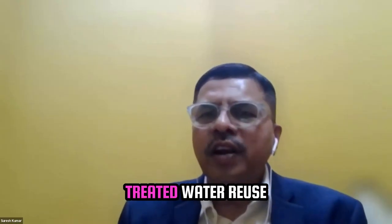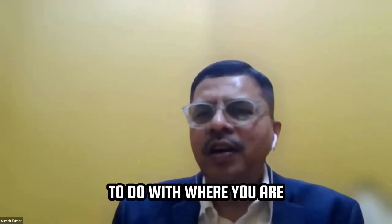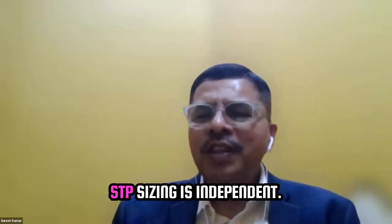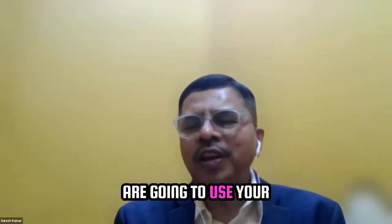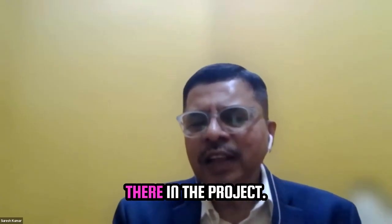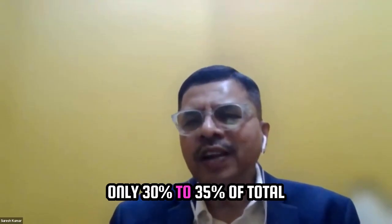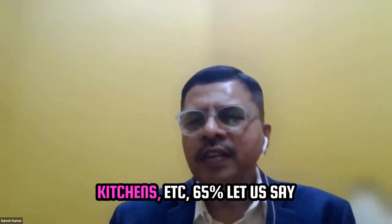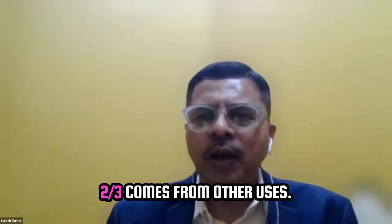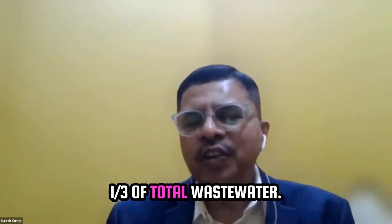Your question is, how does treated water reuse affect the STP sizing? No, STP sizing has got nothing to do with where you are going to use the water. STP sizing is independent. STP sizing is based on your usage pattern, how you generate, how many people are going to use your STP, or how many people are there in the project. Whereas gardening and flushing typically uses only 30% to 35% of total sewage generated. The rest of the water is coming from your bathrooms, your kitchens, etc. 65%, let us say 2/3 comes from other uses. Your flushing, that is water commodes, generate only 1/3 of total wastewater.